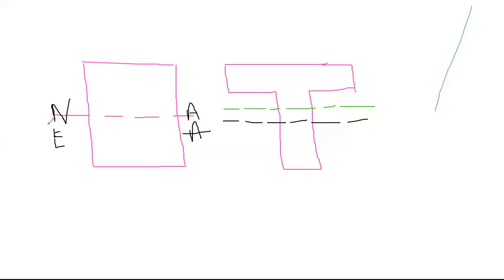this is neutral axis, and in case of a rectangle or a circular section or I section with both flanges having the same dimensions, they will coincide. So what exactly is your equal area axis? If I can divide the given figure into two equal parts, equal parts means area should be same at the top as well as at the bottom.